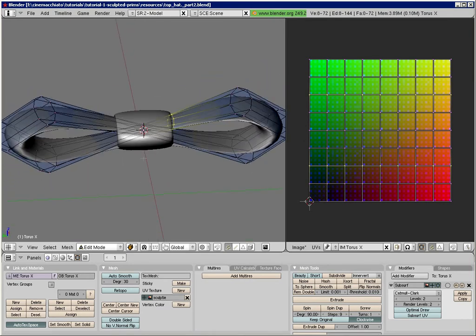Deselect all vertices, and watch what happened to your sculpt map. The new loop is seen in the sculpt map as an additional row of vertices. You immediately see that we have increased the vertex density where we added the loop. And this is exactly what we wanted to achieve. Have more vertices along the critical areas of the sculpting. I will show you this again in a moment, but let me introduce another very useful feature of Blender beforehand.